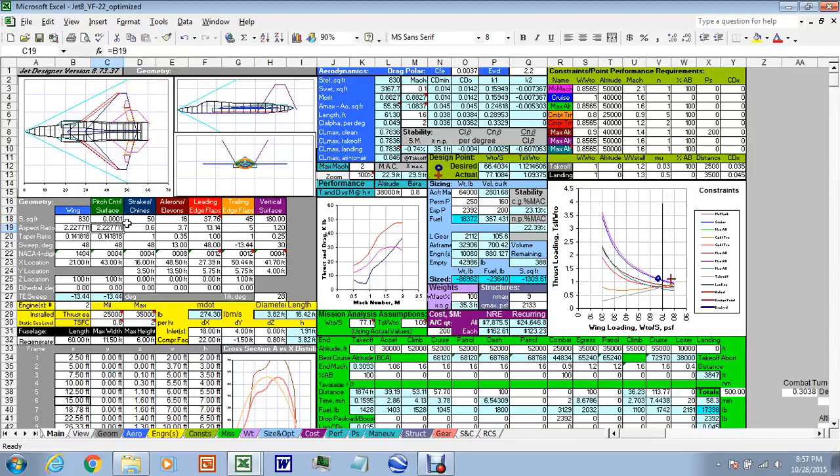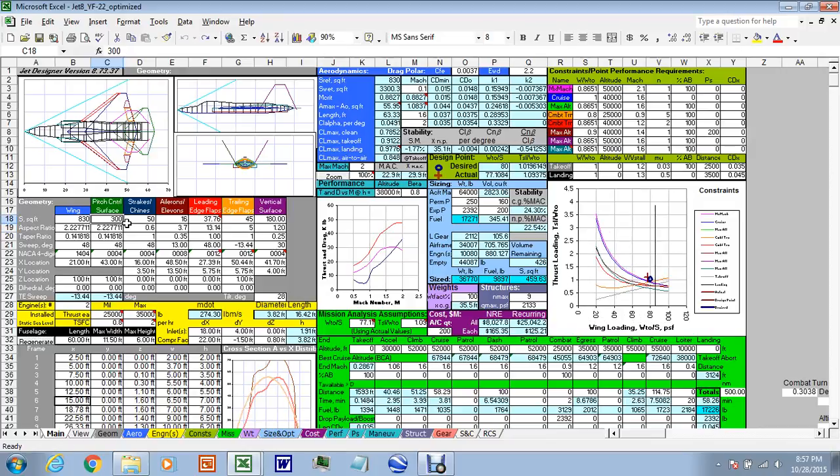Well, isn't that interesting? The aircraft got more stable. In one sense it makes sense because we got rid of 1,000 pounds of weight very far aft on the airplane. So the CG moved forward and apparently got closer to the neutral point. But that means the neutral point didn't move much. And so why would that happen? Let's hit Control Z and let's see if we can investigate and see what's going on. Control Z, our surface is back.